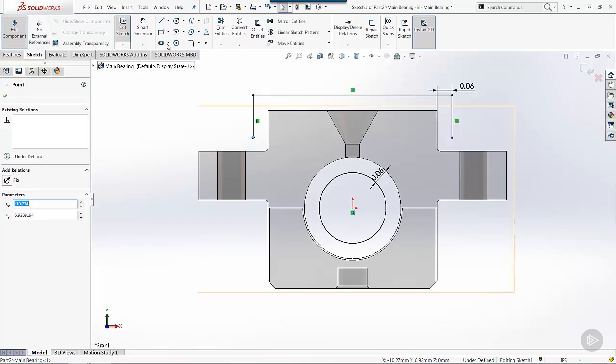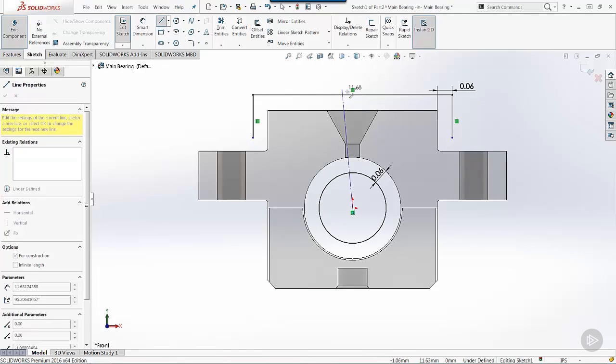Another thing that I like to do is have lines of symmetry established using center lines. And so maybe I want to come in here and specify what our center line is going to be, and that might allow us, as we draw the rest of our geometry, to get to a point where we're minimizing the clicks to get that geometry. And so I'm going to sketch this in.